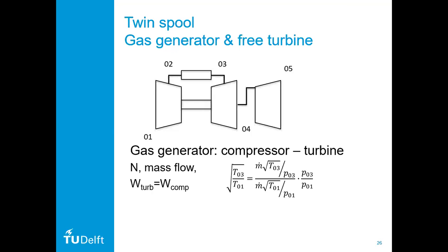I think at the end of this class we will also discuss limits of stresses and things like that. And then the optimum compressor speed: normally you run a compressor at transonic speed, so Mach 0.7, 0.8, then you have the optimal performance, and otherwise you get choking. So they really have a limited area of operation, otherwise you enter surge and stall limits. But you have all kinds of things like I said, stall: if you start up a gas turbine and compressor, you have all kinds of different rotational speeds where you go into stall.